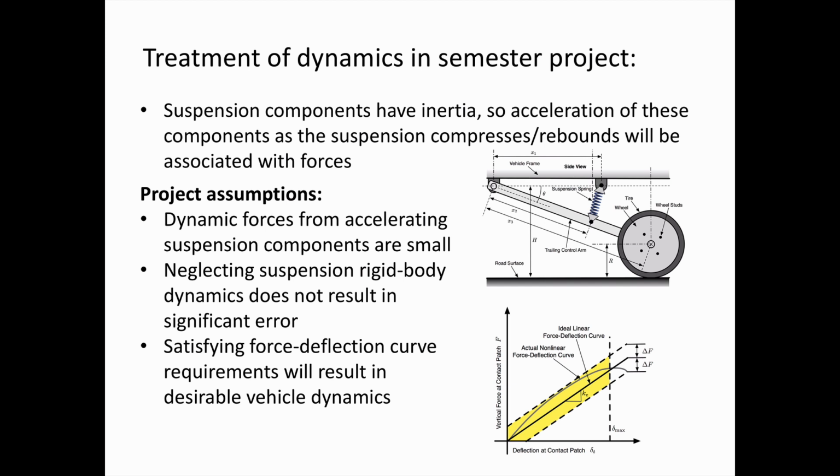We're also making this assumption I've stated before that if we meet the requirements for the force deflection curve, namely that it stays within this yellow window, that we are going to have good vehicle dynamics. And that is a pretty big assumption. If you were designing an actual vehicle, really you should simulate the vehicle using a full nonlinear model.